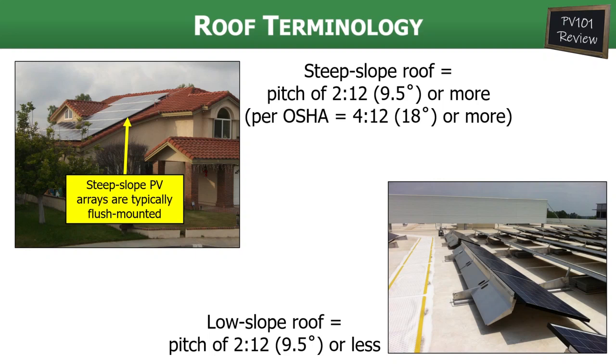So if there's no slope, water would just pond on this roof, which is what roofers try to avoid at all costs. So when you're speaking with roofers, never call it a flat roof, always call it a low slope roof. If you use that technique, you'll seem more knowledgeable in the industry and not look like somebody who doesn't know what they're talking about.